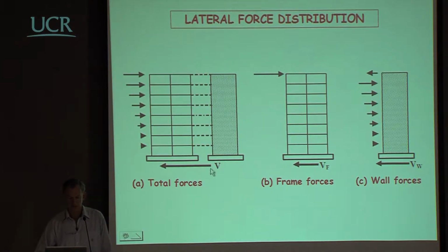And we've said that this provides, at this stage, an unknown value for the base shear, but we are making the decision that whatever that value is, we're going to carry beta times V by the frame itself as a base shear, and we're going to apply that as a single load at the top, meaning that the shear is constant all the way down the frame system.